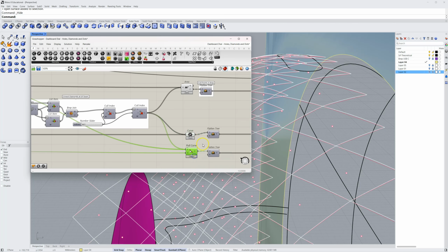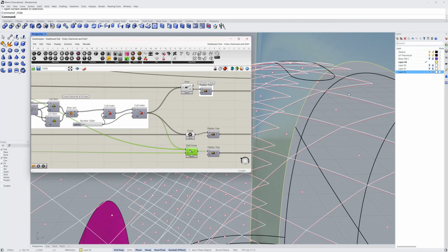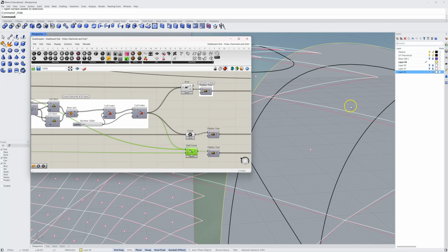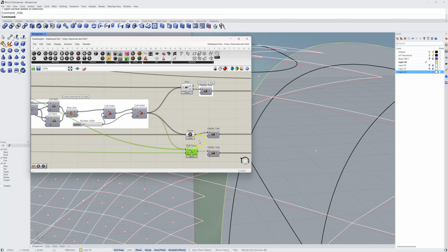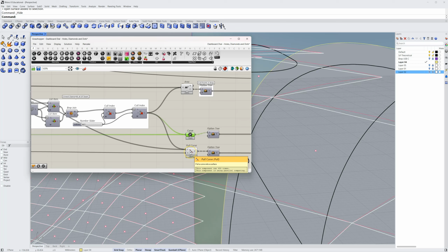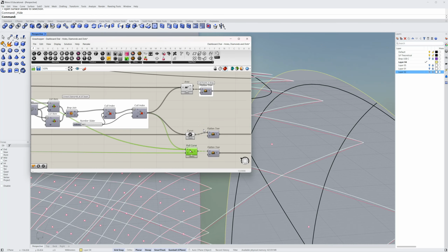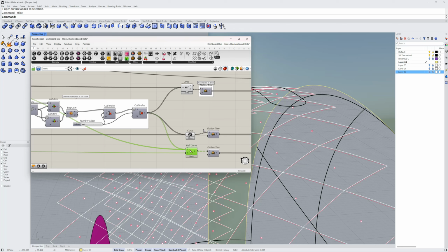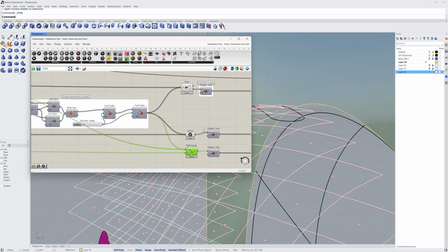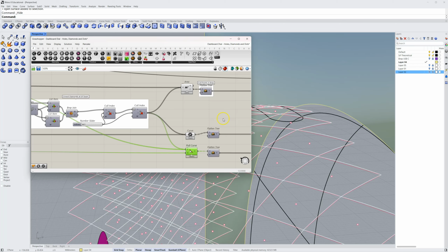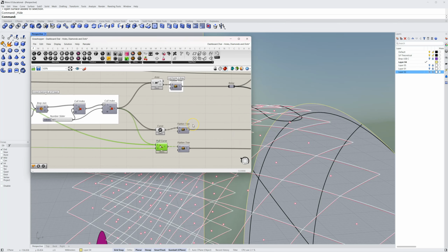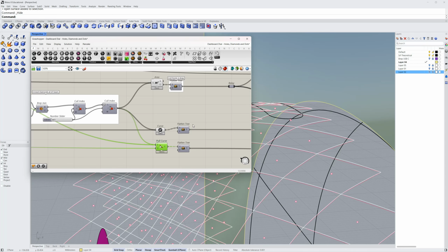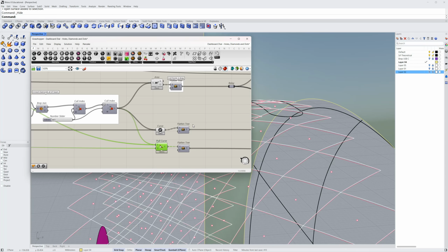And if I preview this on, and I zoom in, you'll note that these curves in white vary from the original curves because I pulled these curves up onto my surface. And this is really important because now when we split and trim and join our surfaces back up, they'll actually go together again and become one surface. If you don't do that, you'll get three surfaces and they won't join. Okay, there's nothing you can do about it. They're almost impossible to join.